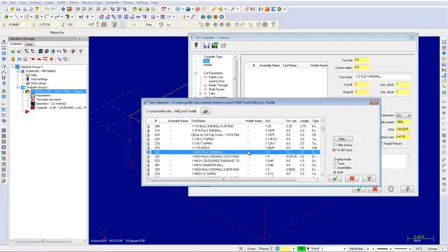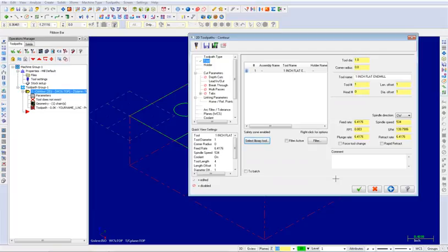Select the OK button once complete. Your tool will appear as shown. Note that the tool number is automatically set to 1, based on the option that we selected earlier, Assign Tool Number Sequentially. Now, enter in the comment, Machine the 0.375-inch step.